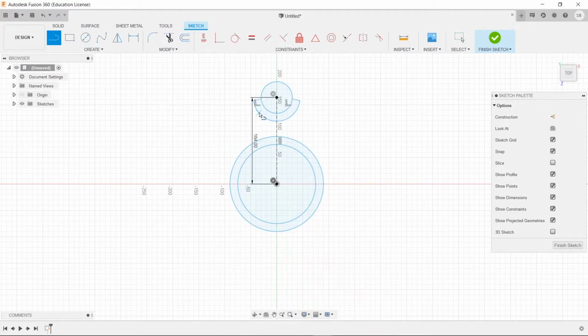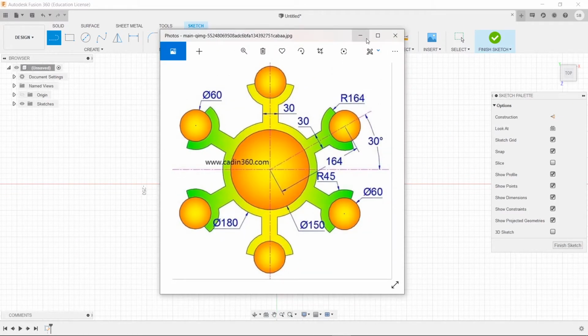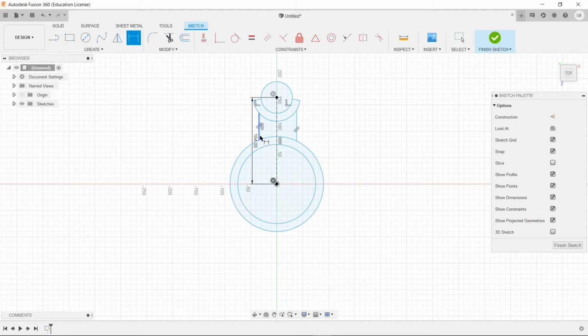So we're going to just draw anywhere on this and make sure that it's just tangent or perpendicular to the y-plane here, or this line here. So basically, we have these two lines. Now, obviously, they're a bit thicker than these. So what we're going to do is press D, and that allows us to choose our Dimension tool. So that's going to allow us to dimension these, and we're going to type in 15 millimeters and press enter. We're going to do the exact same thing over there.